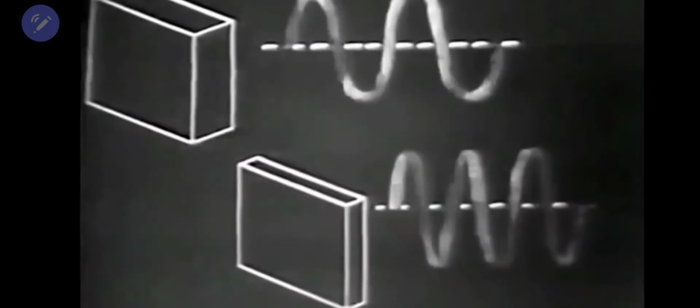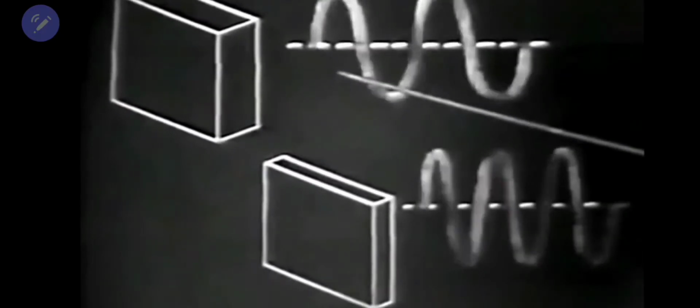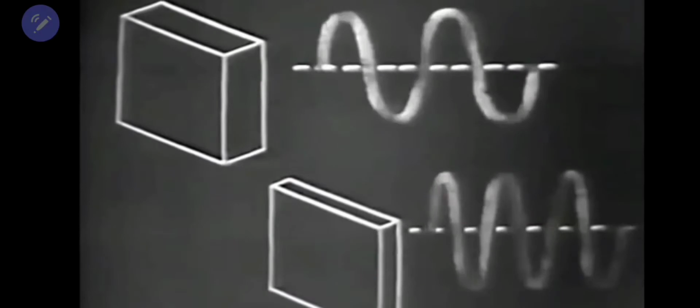Now, all crystals look the same, but not all will exhibit the same characteristics. Its frequency will be dependent upon its thickness. Let's take a look at two pieces of crystal cuts and compare this difference in thickness. As you can see, the thinner cut here, the thicker cut here. We're indicating here that the vibration of this thinner cut, or the frequency, is greater than this cut. Now, this will always hold true. The thinner the crystal cut, the higher the frequency of oscillation.